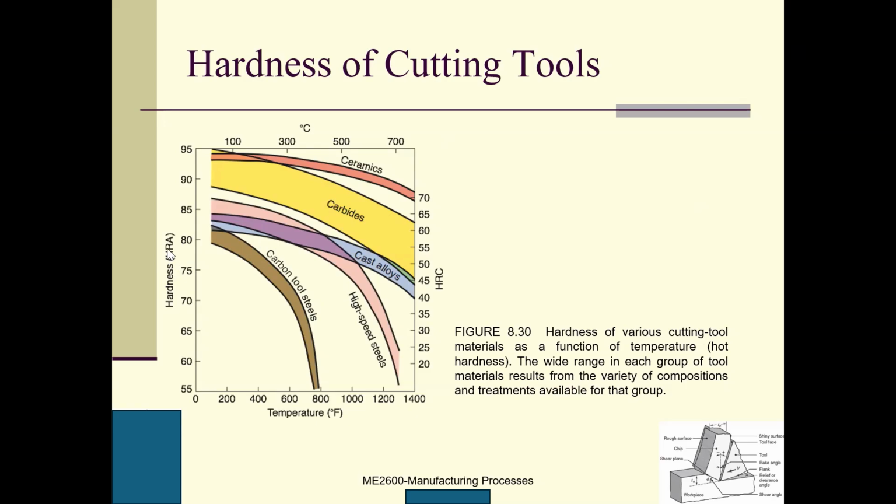Rockwell. H is hardness, R is Rockwell. Rockwell, ROCKWELL. There are scale A, scale B, scale C. For our ME lab, we use scale C. That's the reason the specimens are designated as HRC, then a number. So HRA means the Rockwell hardness in scale A.